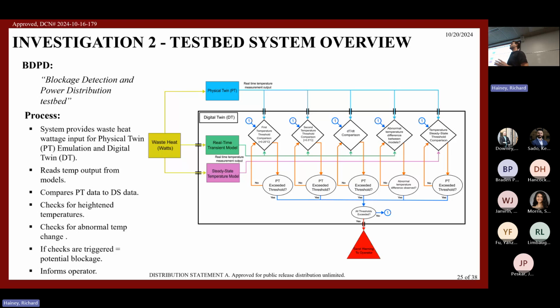If you're seeing a decrease in temperature within the neighboring modules of the one you suspect a blockage is occurring in, you would normally see the flow that would be going to the blocked module is now being redistributed out to the other modules. So with the increased flow to those modules, you would see an increased heat transfer from those modules, and thus a decrease in the temperature. You could use this knowledge to determine which one of the modules has potentially developed a blockage.